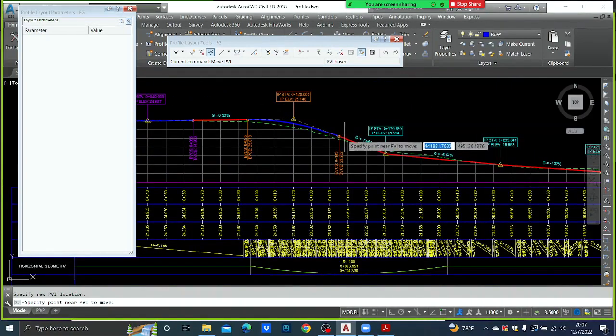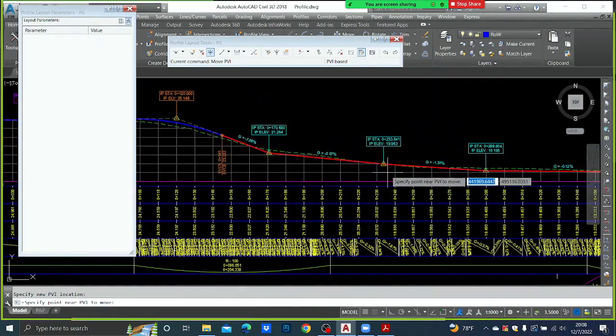But remember again, this should be minimum 25 meters. So that means effectively from 120 to here it should be 50. Why? The length is 50. In vertical alignment you don't measure the length along the curve. You measure it along the horizontal plane, right? That is what is given. So it should be, yeah, 170 is okay. And again you can see here this IP is not necessary, so you can remove it. Like this.